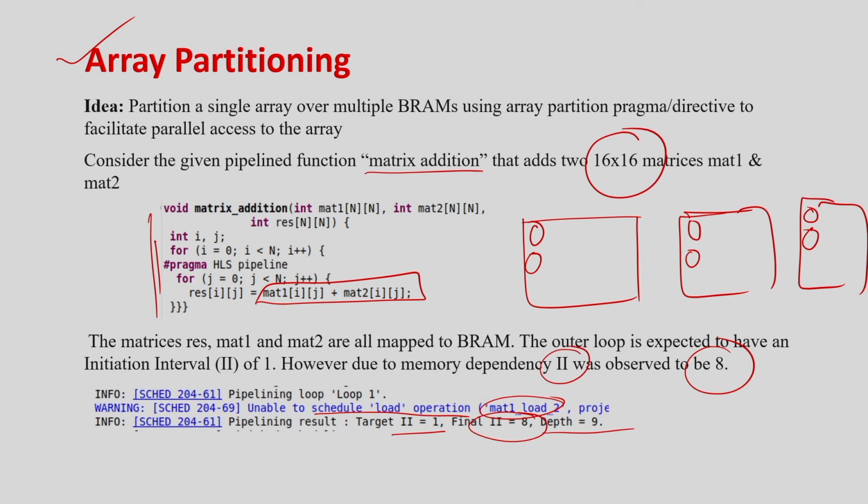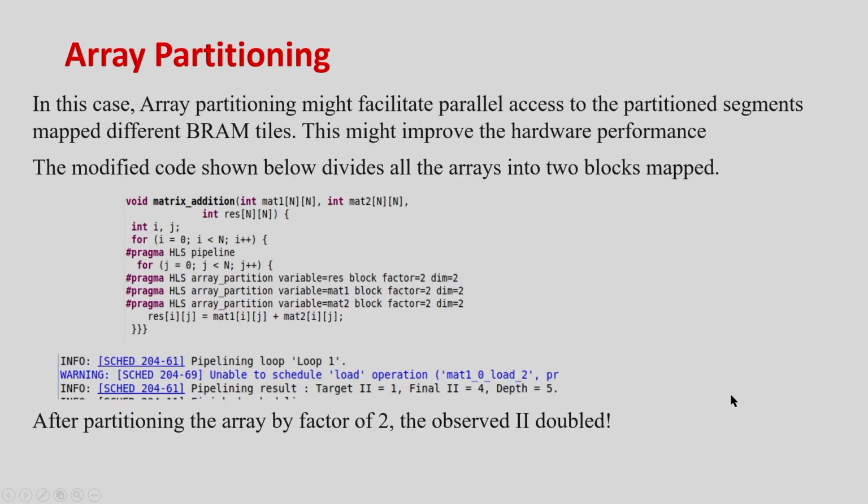You have to go deeper to understand, because these things will be split into 3 address operations and can be split into more operations, that is why we have a depth of 9 there. So, you can actually run it and see the schedule and you can understand it much better there. But the problem is that because of so many memory reads, it is creating a problem, right. So, what we can do is basically unroll it.